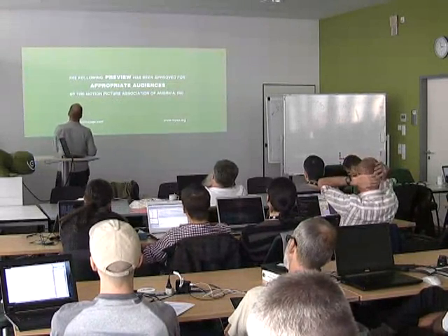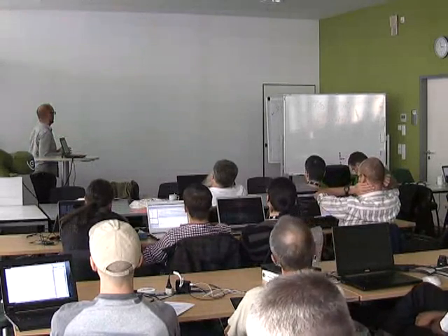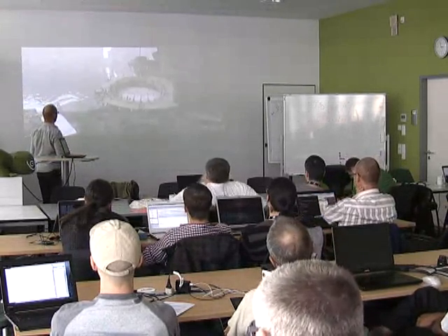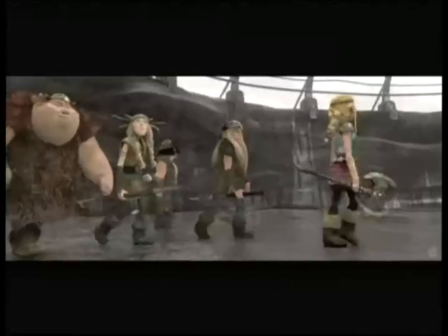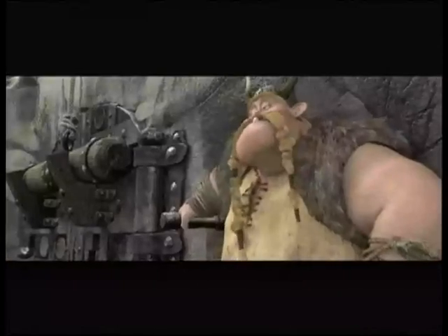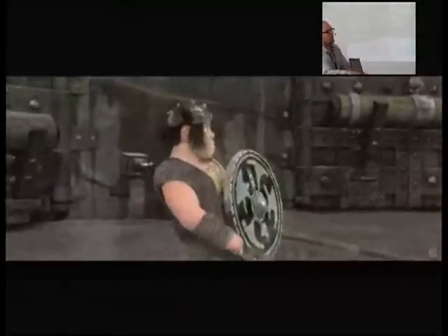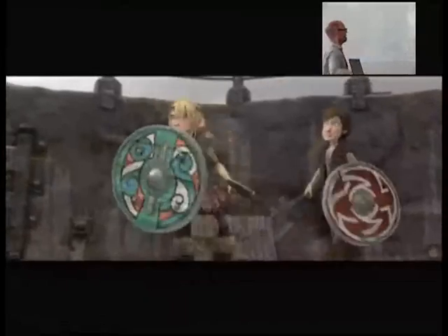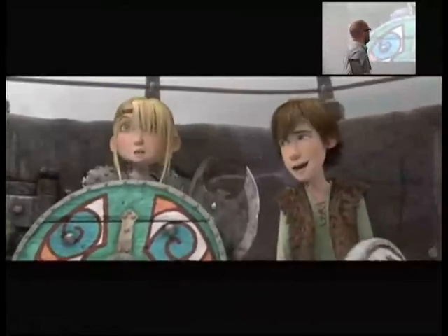And so what this is, is GStreamer using libva to decode, and then pushing the YUV frames to the compositor every time there's a new frame ready. And this is not using an overlay, and we have a slight incompatibility problem in our hardware, where our hardware decoder can't actually decode into a format that we can use with our overlays.